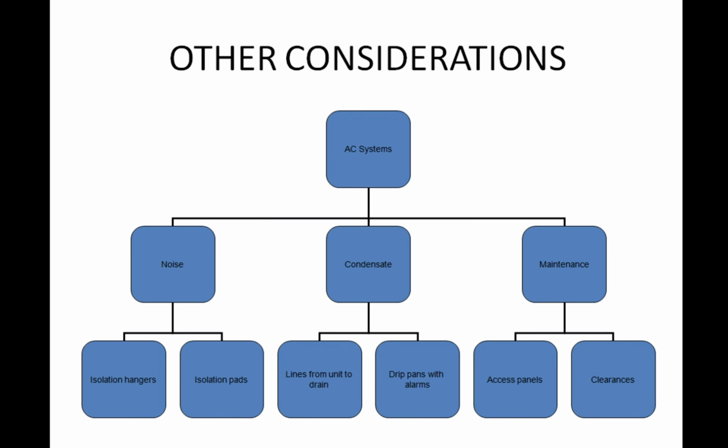So we have isolation hangers, we have padding that goes between that, and we also have to make sure that it's designed such that those duct runs aren't being overburdened by the flow going through them to the point that they're vibrating or rattling. So all that's taken into consideration when your HVAC system is designed and then installed.